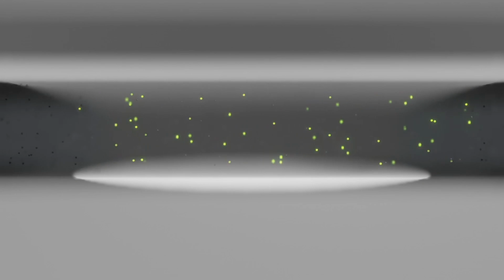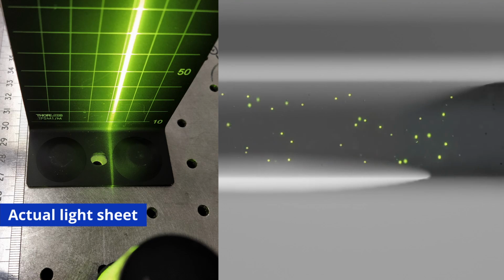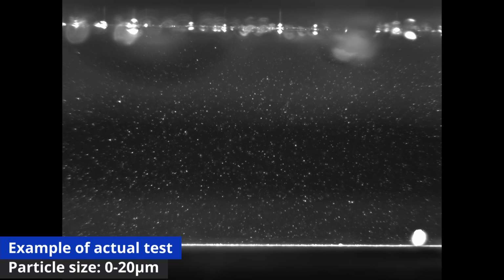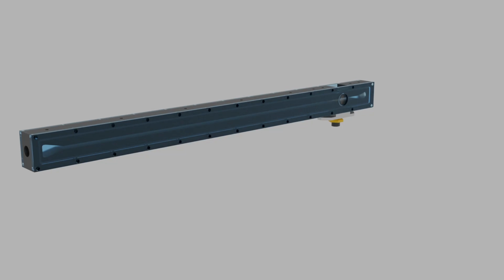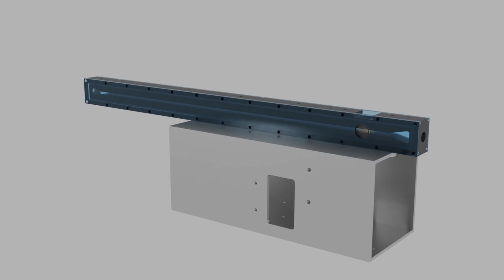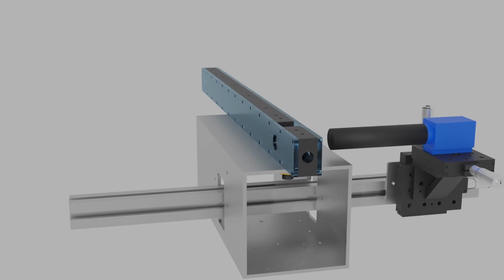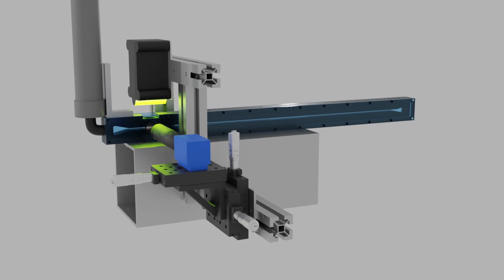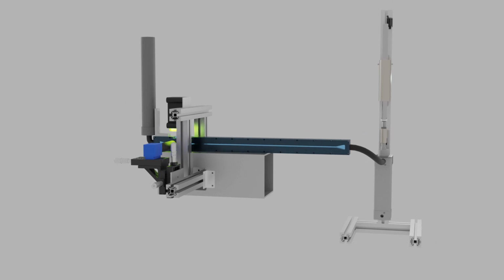A 2D PIV measurement requires a light sheet such that the particles that are not in the camera's focus do not light up. The shutter speed of the camera should also be set fast enough in order to prevent motion blur. These two points are very important to create clear pictures such that the particles can be identified and tracked by the software. The channel is mounted to a big aluminium tube. To that tube an aluminium extrusion profile, with the camera and lead, is mounted. In this way the camera and lead positions stay fixed relative to the channel, even when moving the setup around.